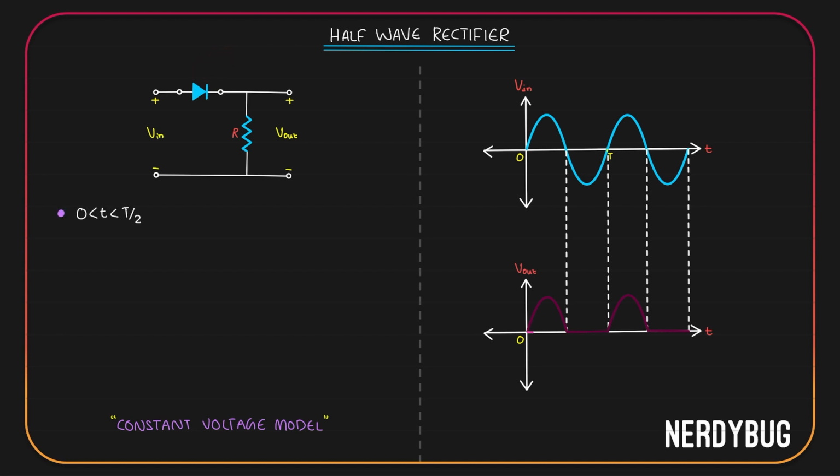So, the circuit model will look like this. Using KVL, we can write V output is going to be V input minus Vk. If we plot it on the graph, this is how it will look like. The output was 0 until Vin took a particular value that is equal to the knee voltage. Now, over here, input again becomes lower than the knee voltage, and hence the output becomes 0 there also. Let us show it on the graph like this.